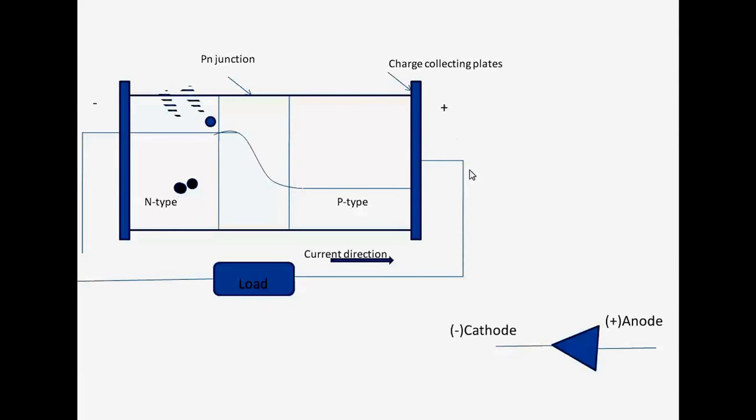Actually, only the photocurrent is usable. From the useful light, only the photocurrent is useful. So part of the light will be wasted in the form of recombination current. So this is one of the causes that decrease the efficiency of the cell.